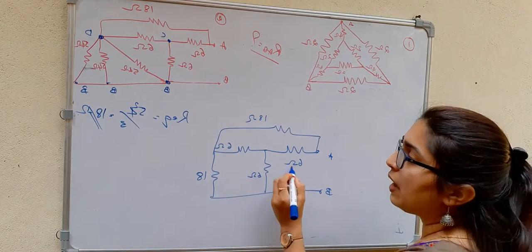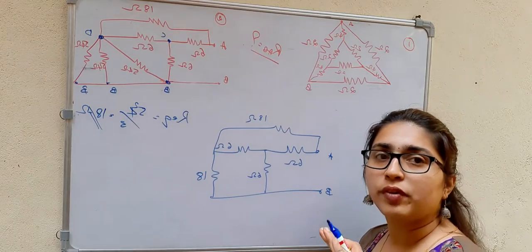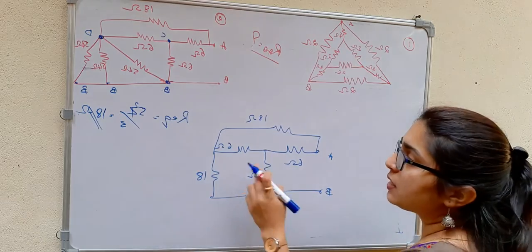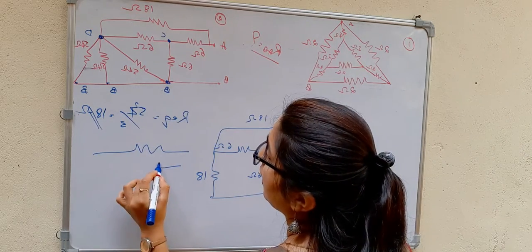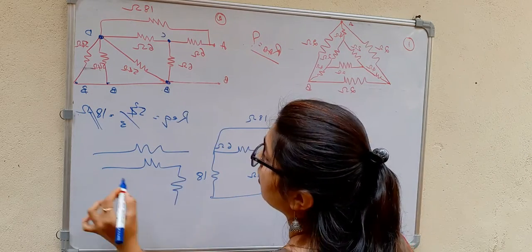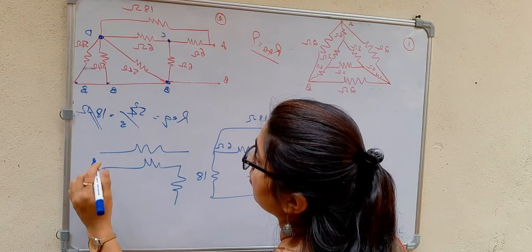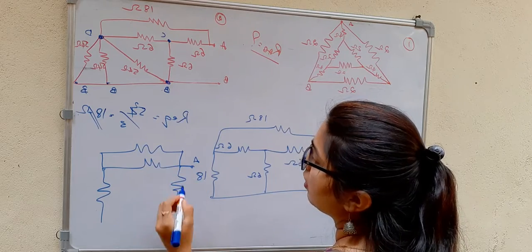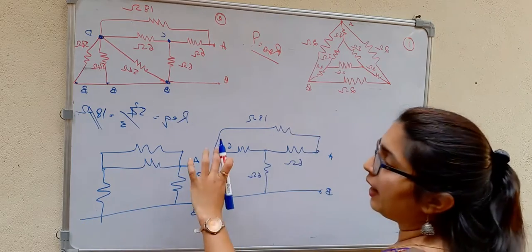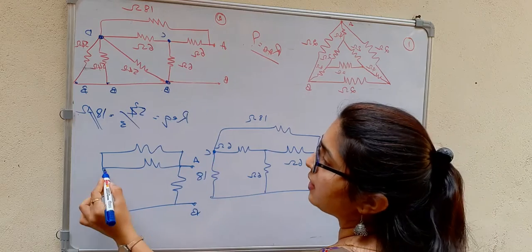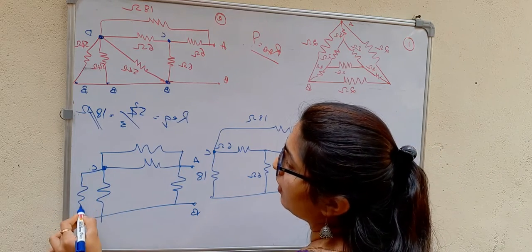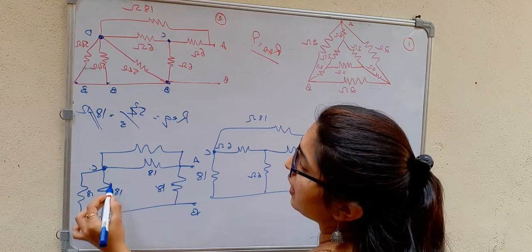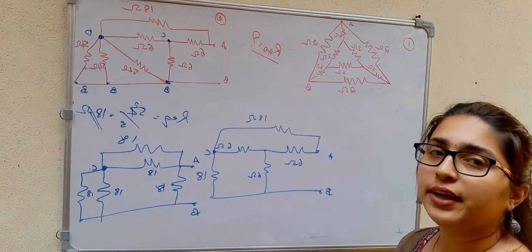Okay, so that means we have equal resistance is 6. So when we are converting from star to delta, it will be multiplied by 3. So 6 3s are 18. We have 18. So this is A, this is B, and again we have from this terminal, if I consider, another resistor 18 ohms. This is 18, this is 18, this is 18, this is 18. Now all are 18, right?